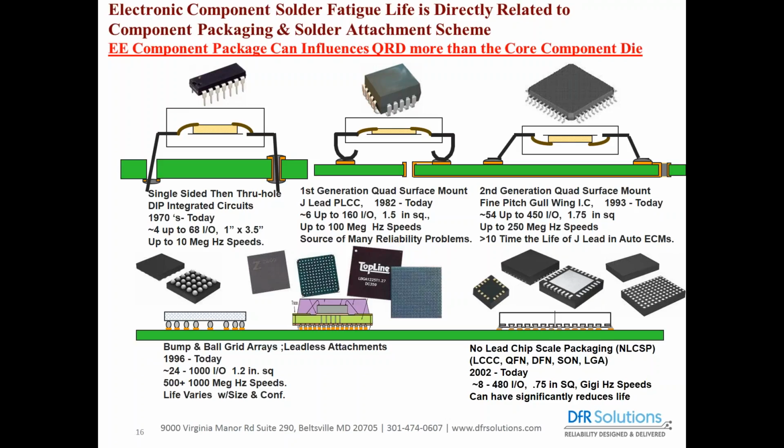These, in their early days, also had problems until we developed methodologies to reduce the stresses of the solder balls to get their life up. And what we have today is the onslaught of what are called near chip scale packages, leadless, bottom terminated components: quad flat no-lead, dual flat no-lead, and so on.